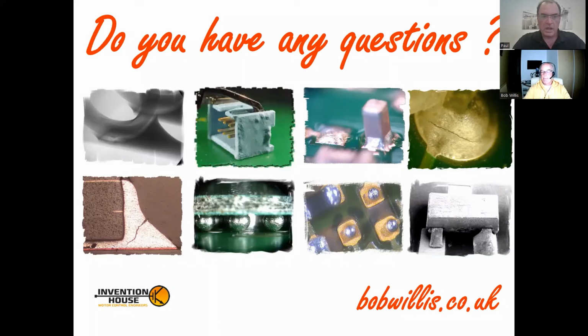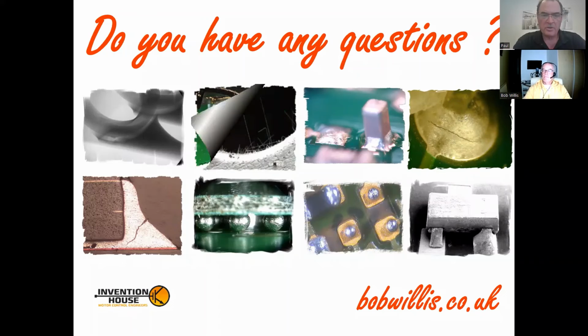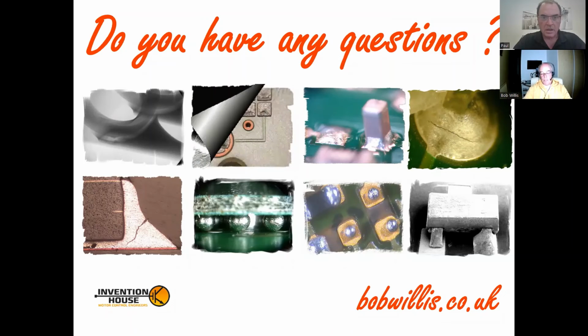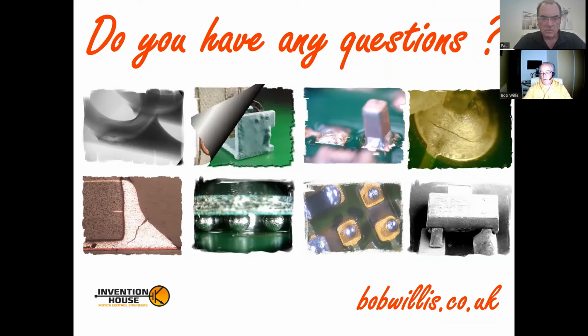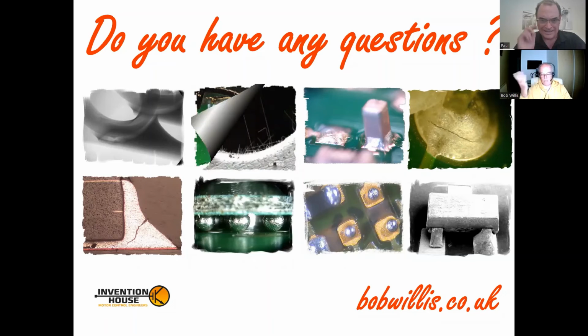Okay, and then we have a question, micro bubbles / foamy texture of coating. Elaborate more on the reliability impact. It's a good question. I tend to find that you've got potentially more issue. It's just like soldering. If we talk about voids in solder joints, people get very excited when you've got voids in solder joints. Well, we've had them for years.